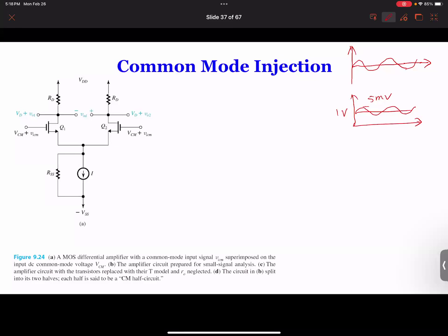You're right, the transistor width and length can hardly be exactly identical. It could be a little bit different, and plus other things too in the MOSFET. So the result of that change is the GM, basically, the GM, VA cannot be exactly the same either. So GM is going to be slightly different. And it could be 1% or 0.1%, whatever that percentage is going to be. So that can cause this thing to change.